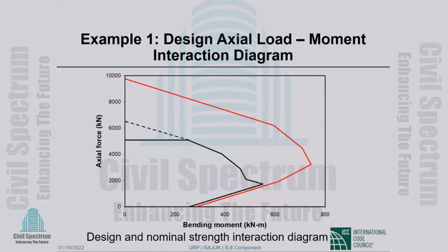The only problem I see, I don't know that there is a prohibition, but something should be checked out. If there is a steel shape in a column, as I mentioned earlier, there will be redistribution of forces between the concrete and the steel.